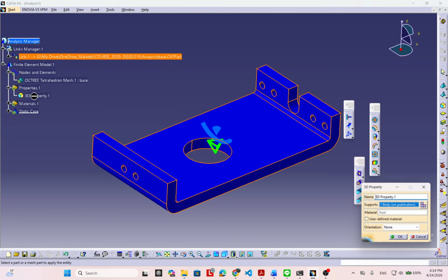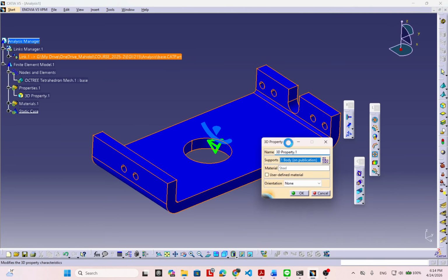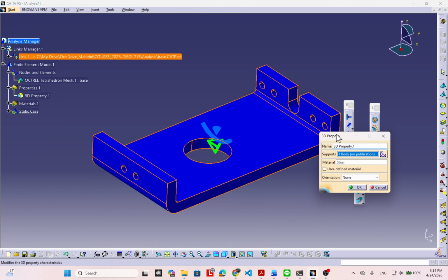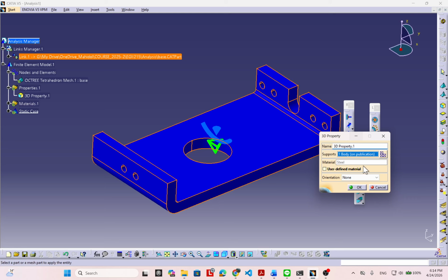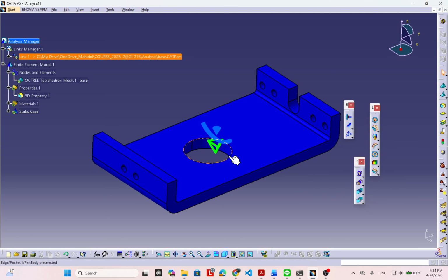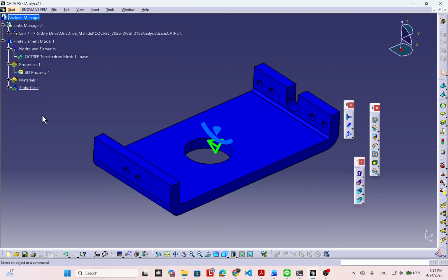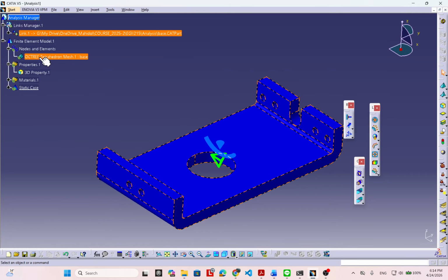Double click on this one. This command box can be set up about the material, right? Right now I set up the steel material. Okay, already done. I set it up in the part design before. Click OK. Okay, right now I already did 2 steps, right? And the octahedral mesh, I call it. Another name is the solid mesh.